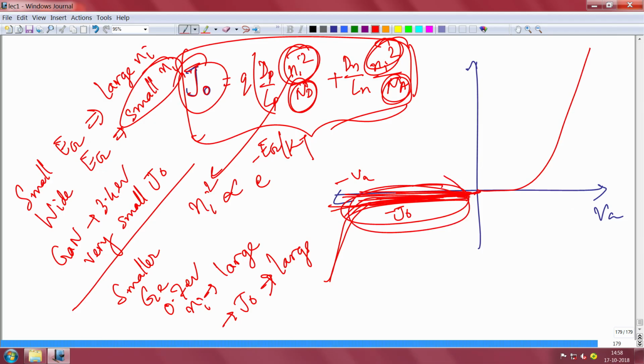Okay. So, we will wind up the class here. We have finished up the PN junction in non-equilibrium. Under the application of forward and reverse bias, what happens? We have derived the expression for the current. So, this is in a sense the PN junction fundamentals that we had to learn to be able to understand many other devices. The forward bias and the reverse bias current expressions we have derived, the physics of that we have explained, okay, the diffusion component and all.